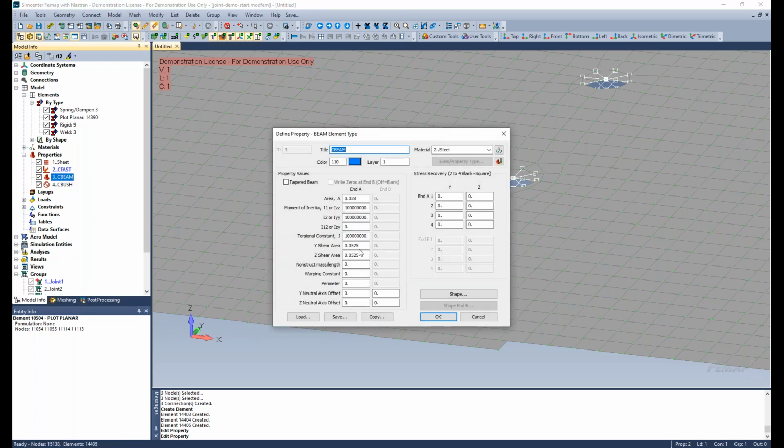The beam is a bit more complicated because I had to take its stiffness and then, based on the modulus of the material, in this case steel, and its length, calculate what the shear stiffness would be based on just the shear modulus, the area, and the length. Then I had to define the shear area factor here to make sure I got the correct stiffness. So some additional calculations are required above me on calculating stiffness in order to use the beam, which is why I said generally I think beams are more trouble than worth, unless you are doing bolt forces. But you can do it.